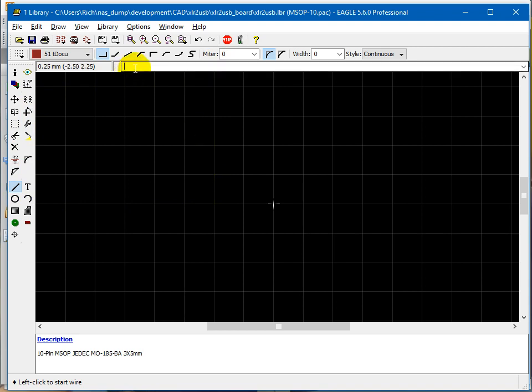You can do the wiring in a couple of different ways. You could click around and use your X and Y ordinates here to help you out. But I like to use a lot of command line stuff. So even though I'm in the wire command, I just always type wire. Wire. Use parentheses to give you your 2 coordinates. Unlike other CAD systems, there's no commas in between the 2 ordinates of the system. Later on, we'll talk about relative coordinates, but for right now, everything's absolute.